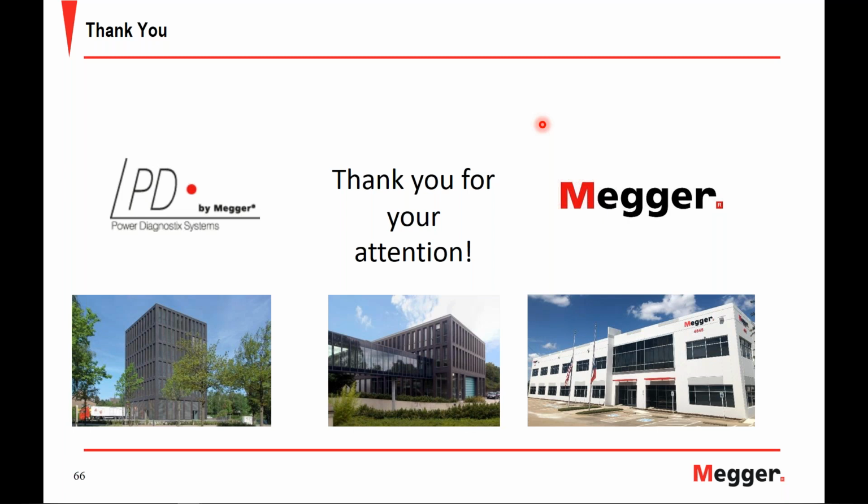So it's definitely beneficial if you have joints or other accessories within your cable that could be revealed with those measurements. Tan delta, or power factor, is more of an average measurement and gives an overall assessment of the condition, where partial discharge has the opportunity to find some of the isolated events. So definitely relevant and capable with the ICMflex, yes.